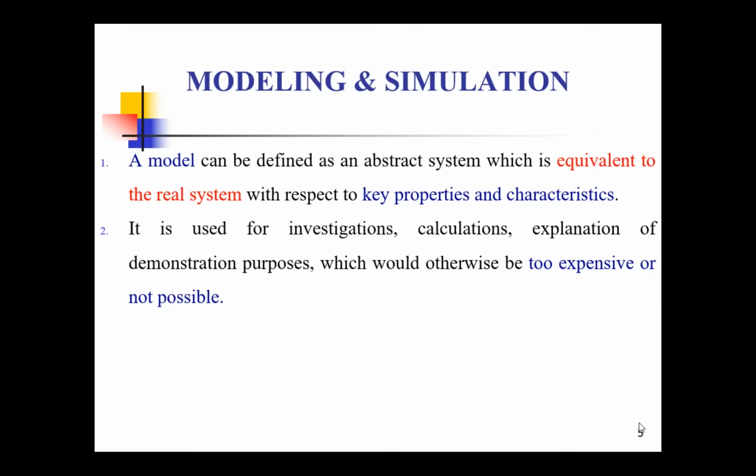So those cutting forces can also be predicted by using these models. It is used for investigation of how a process behaves, and we calculate the outputs, for example the cutting forces and the temperatures, because whenever a cutting tool comes in contact with the workpiece, the temperature rises at the interface. So that interface temperature can also be calculated by these models.